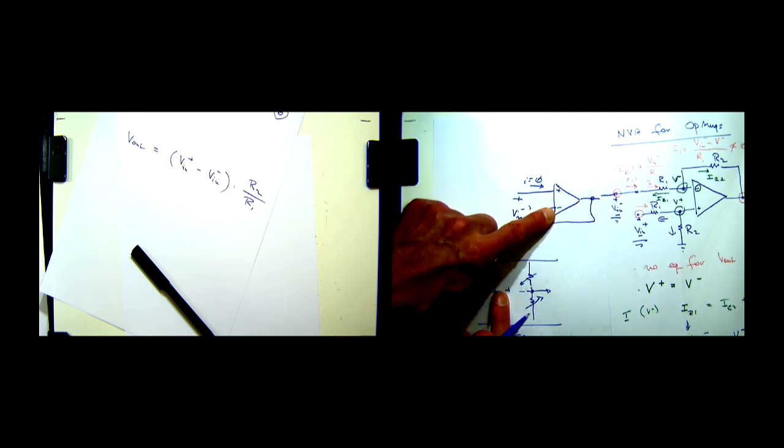But if you connect this circuit here without any of the buffers, you're going to pull current out of these nodes. And that will change the voltage drop across the resistors, and probably changes the very voltage that you're trying to measure. Not good. So you put the buffer one here, you put another one here, and now the current is 0 because the buffer supplies the current, but the buffer itself doesn't take any current at the input. Okay, I'm glad I helped with that one.